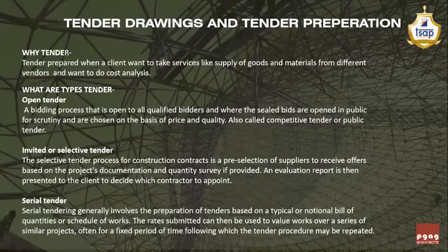In case of serial tender, for example, in a particular work like any bank interiors work, sometimes you happen to work on a serial tender where the contractor quotes for a tender for wooden paneling or only for particular flooring, then the items are going to get repeated in different projects. So you quote for a particular item and not for a particular project. That is a kind of serial tender.